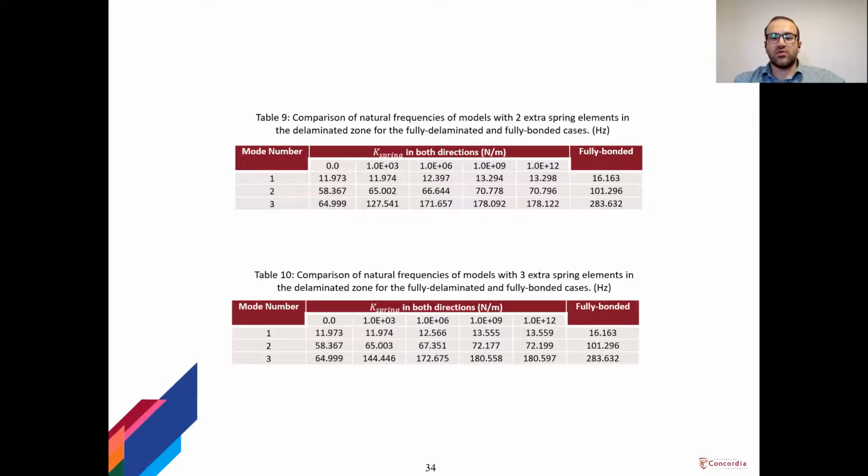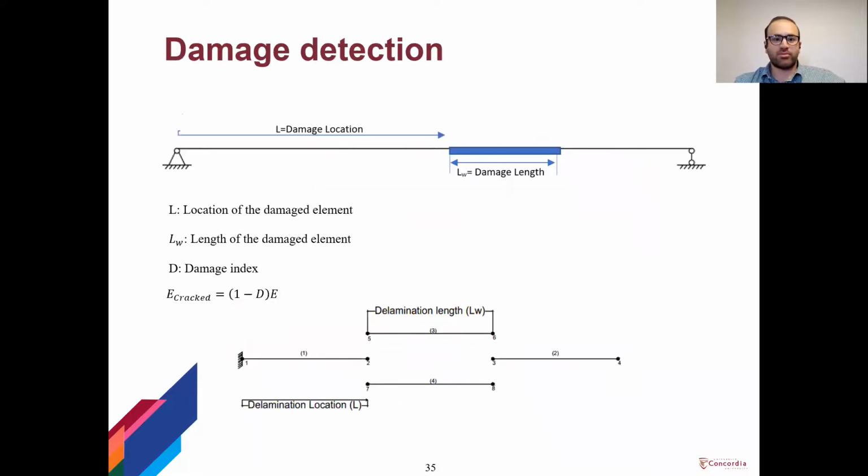By increasing the number of springs and adjusting their stiffness, it is possible to represent the effect of interface friction. However, this discretization undermines the idea of using spectral finite elements method. So the better solution could be inserting a spectral spring element instead of a conventional spring. But this is beyond the scope of the thesis, and we did not have enough time to pursue that.